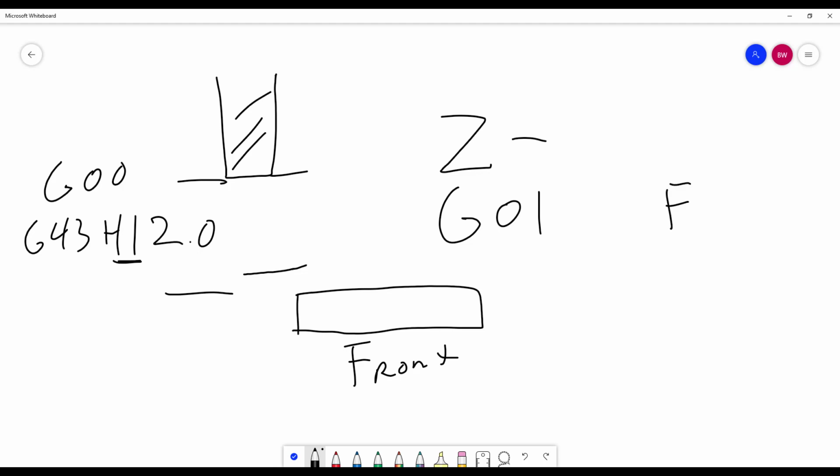So if we go G01, Z minus 0.030 or whatever it is, at a feed of 10 inches per minute, all right, that'll always be 10 inches per minute. It's not based on 5%, 10%, whatever the rapid you're running. Okay, so it's a good idea to always use a G01 whenever you're going Z minus, below the workpiece down this way. So that takes care of the Z, and again, we'll go through an example.